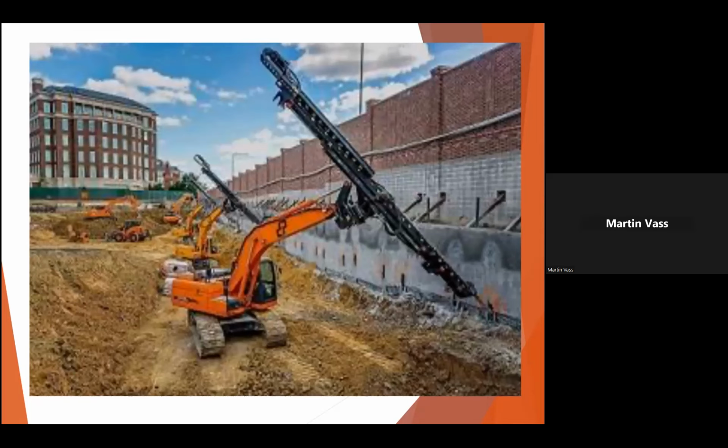So if you're going 2 or 3 basements down, you would want to support these piles with these anchors. Those anchors are put into the ground and stressed with a hydraulic jack. In some cases, you can leave those anchors in the ground if there's nothing adjacent. If you own the property adjacent to where you're building, or it's a park, or it's not going to affect any other property. In many cases, you've got to remove those or detension those cables when you finish the construction work, because you're imposing on another person's property.